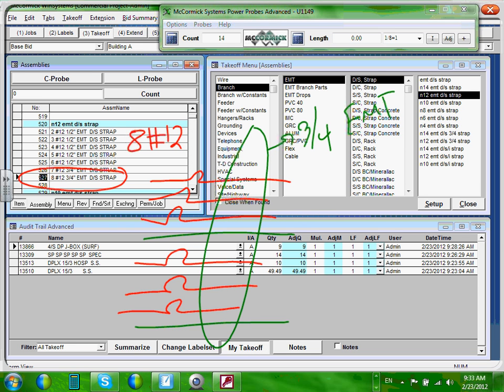out of the top of this panel, and grouped them in a 3/4 of an inch, all the way to a J box in the ceiling or a J box in the wall, and from there I split them to go to different directions. Now that's when you start thinking as an electrician. How do you group the circuits?